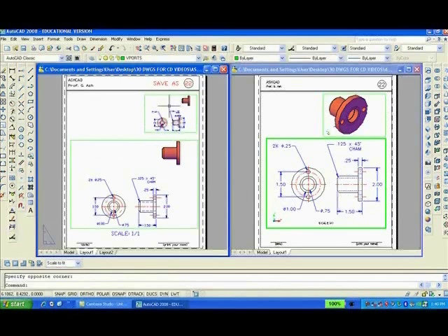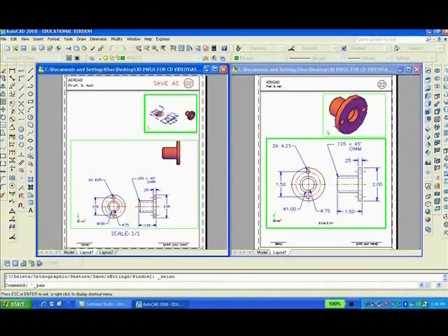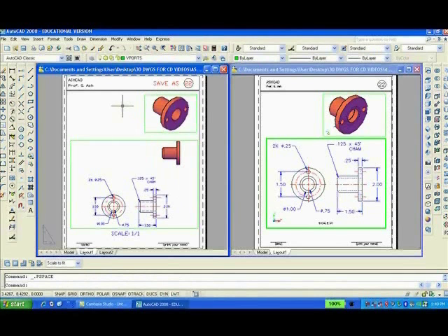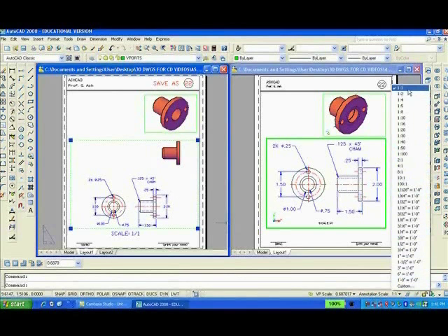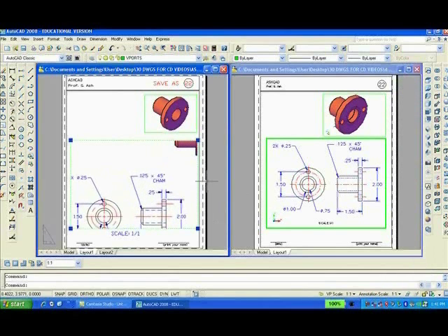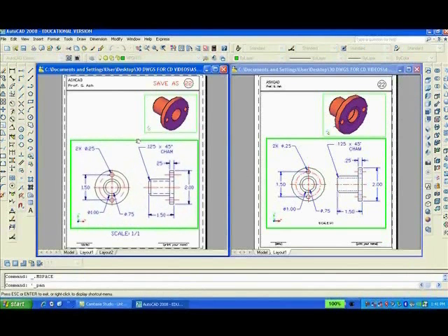Double click inside, southeast, then pan and zoom. We have to set the scale for the 2D drawing. It's 1:1, so we'll go to annotation scale. You can't be fooled by the check mark, that's something else. Click on 1:1. OK. Double click in here and then pan. I hope it'll fit. Yeah, it seems to fit just fine.